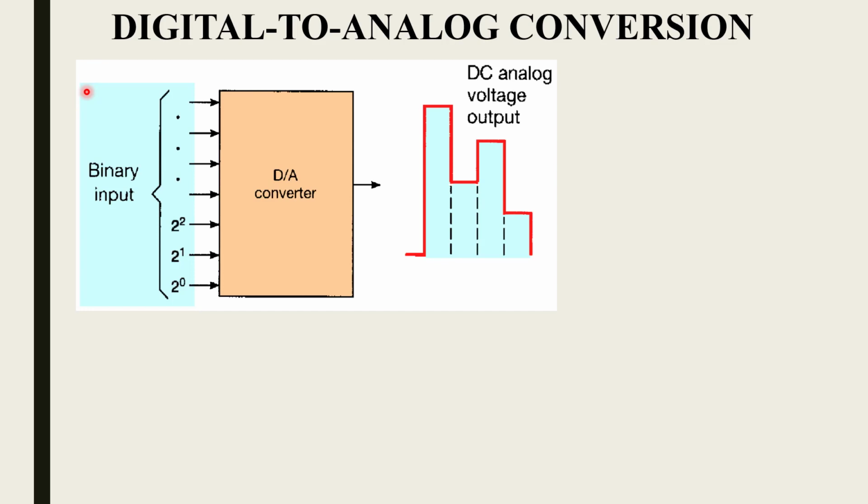Now, what about the sample rate? How quickly do we have to take measurements on those sound waves so that when we go to play them back, they sound the same as they did before? Because if we miss changes that are essential for it to sound the same as it was before, we've got to be looking a lot quicker. Things happen in music. The sound range for human hearing is about 20 hertz to 20,000 hertz. So there are changes occurring 20,000 times per second. So we have to sample at least 20,000 times per second.